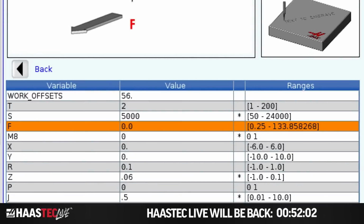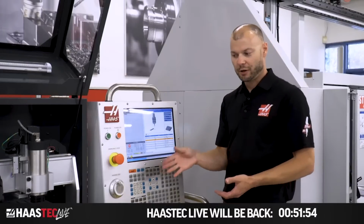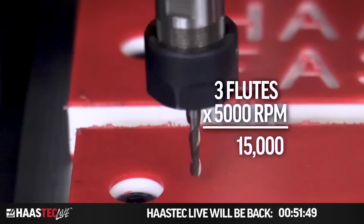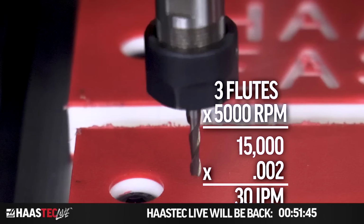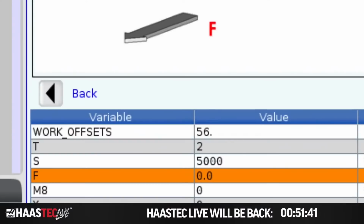Since I selected 5,000 RPM, and I know my end mill has 3 flutes, and I know a good chip load for this plastic material is 2 thousandths per flute, I take 5,000 times 3 flutes times 0.002, which would give me 30 inch per minute. So I'm going to enter 30 with a decimal because this one requires a decimal.